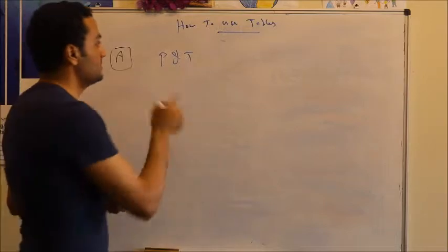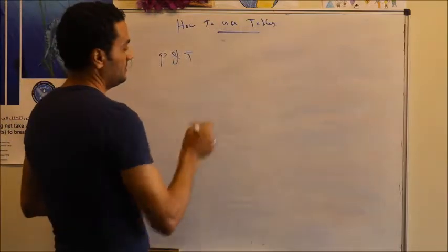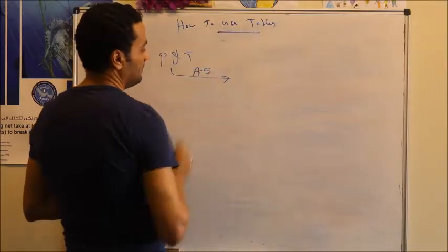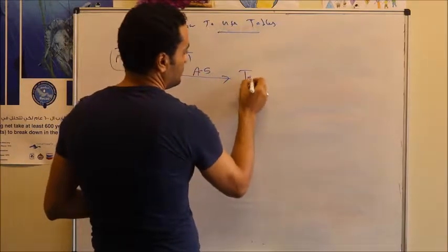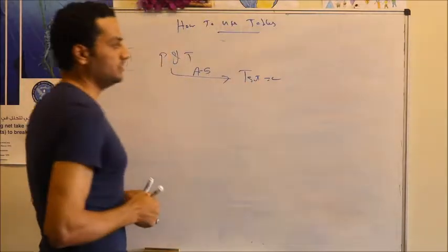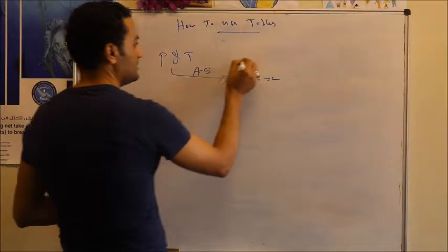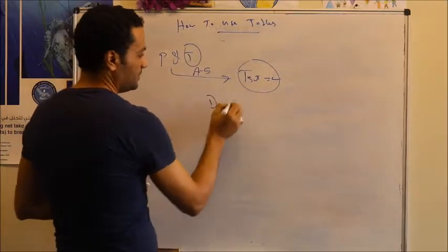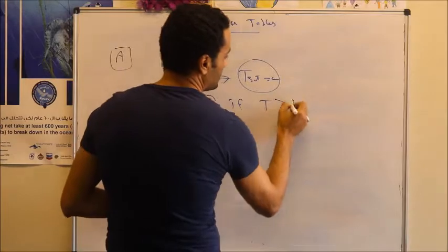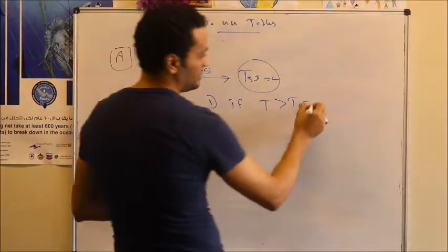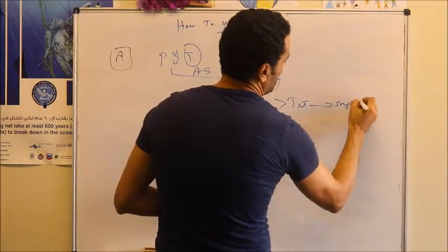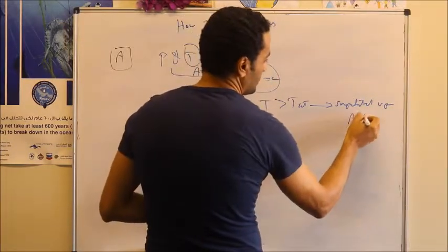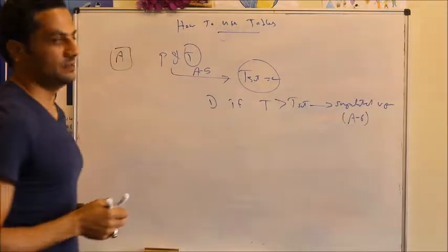Okay? So the steps in this case, if pressure and temperature are given, I will be going with pressure to table A5, then with this pressure from table A5 I can get what? The saturation temperature. And then compare this saturation temperature with the given temperature. So the first option, if we find that the given temperature is greater than the saturation temperature, the state is what? Superheated vapor. And in this case we have to use which table? Table A6 in this case.